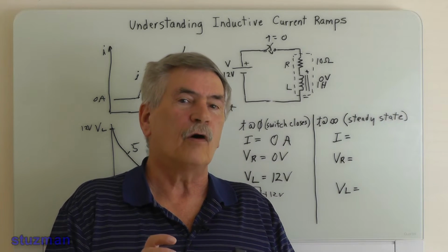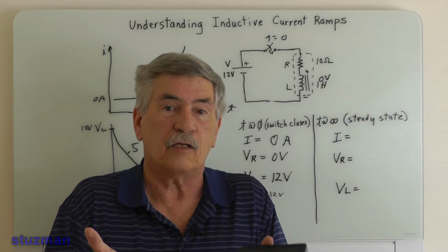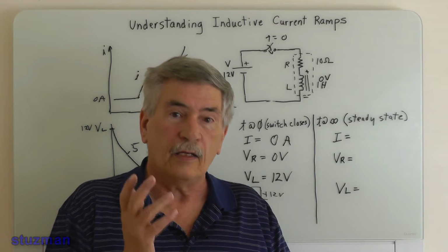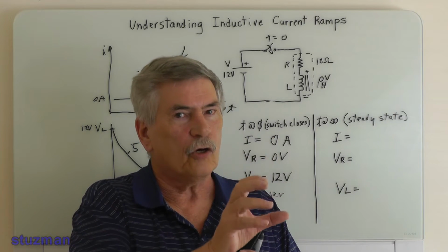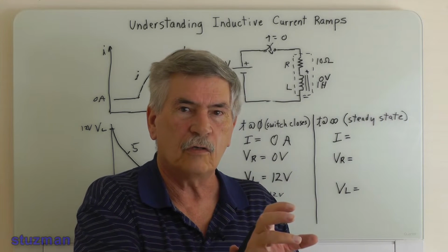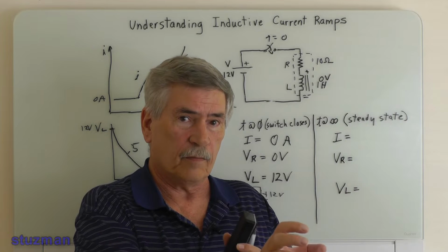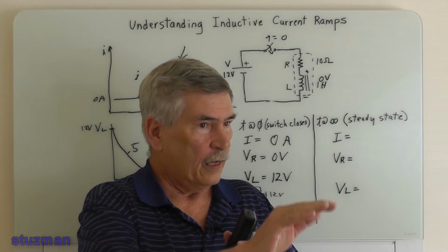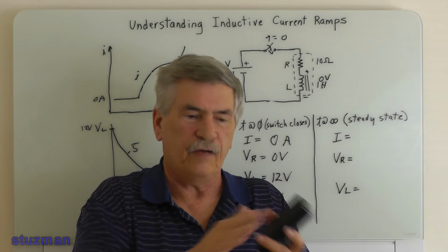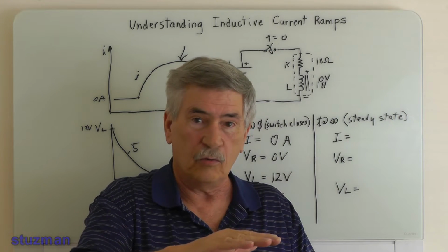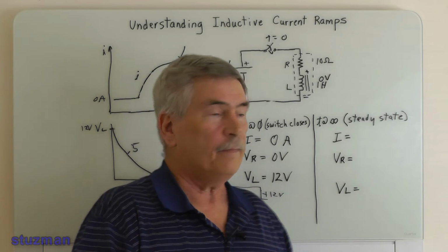Now, I turn up my voltage, my current goes up, and my magnetic field gets stronger. Okay, so now let's say I just crank that voltage right on up and my current goes up, and my magnetic field goes up. Well, I'm going to reach a point where I can keep turning this voltage up, and even though the current is going up, up, up, my magnetic field is going to hit a plateau where it's not going to get any stronger. At that point, that's where we say it's saturated, okay?